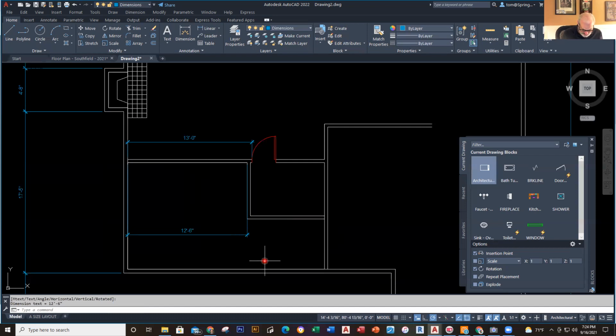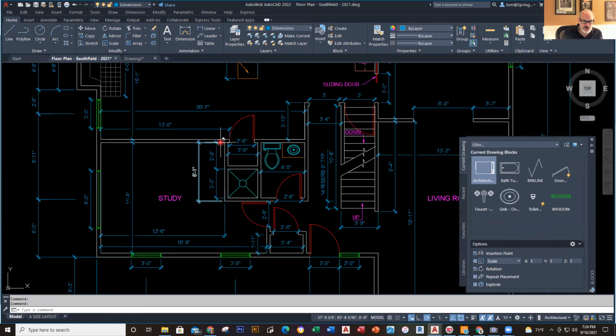Okay, next thing. I've got a 2'9". The next distance I need to put in here is right here. It's 2'9", this to here. That means these walls are 2'9" apart from each other, so this interior to the exterior is 2'9". And this is interior 3 feet. So I could go either way with this. I'll use the 3-foot dimension right here.